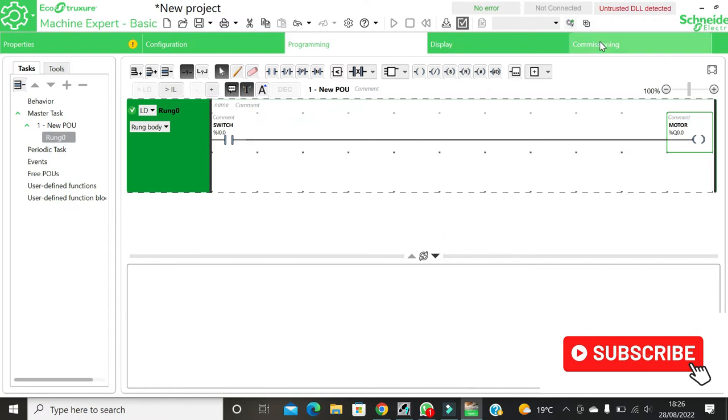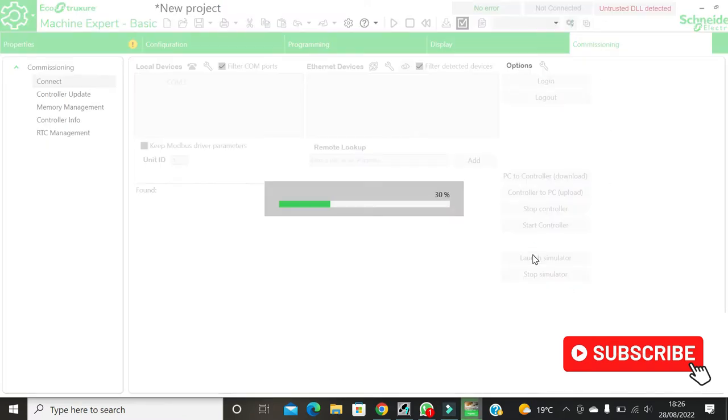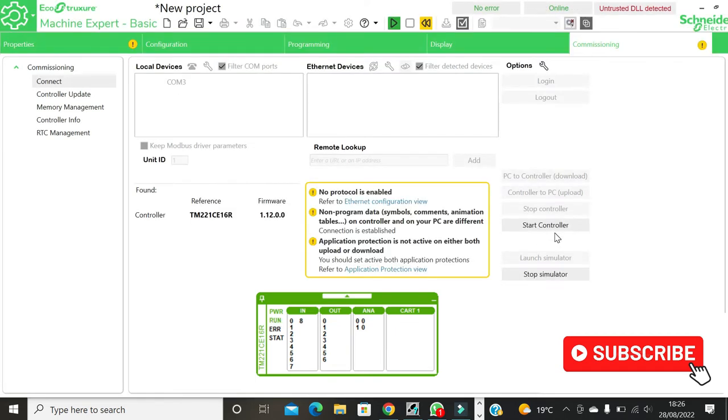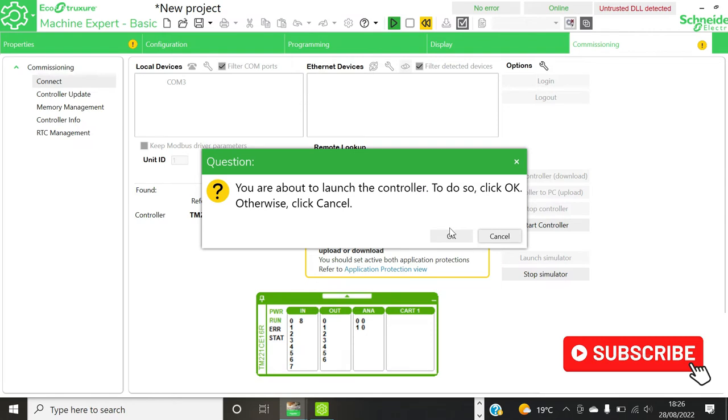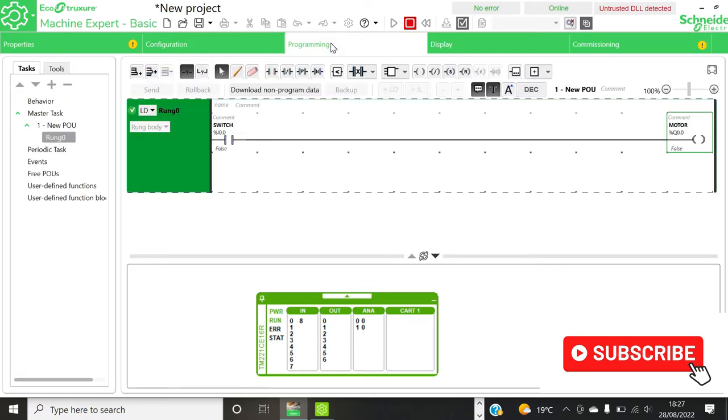and even we can simulate it. We say launch simulator. Then we start controller, and from there we can go back to programming so that we can see our program. If I activate our input 0, you can see the motor comes on, and if I deactivate it, the motor goes off.